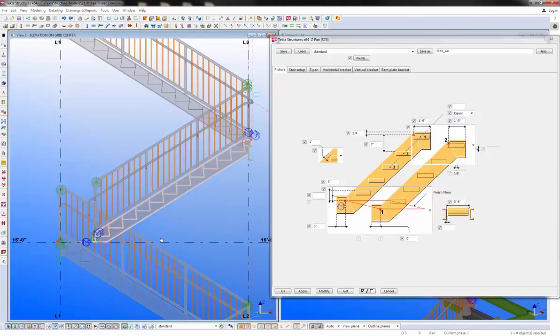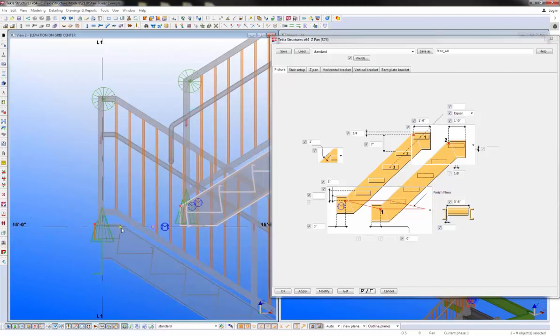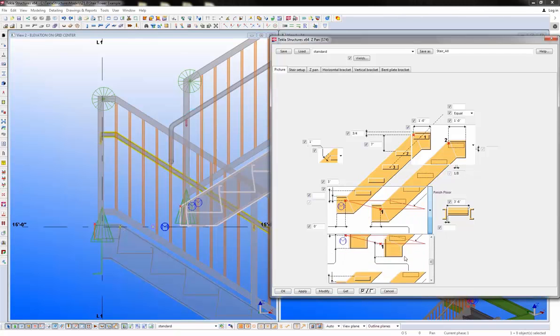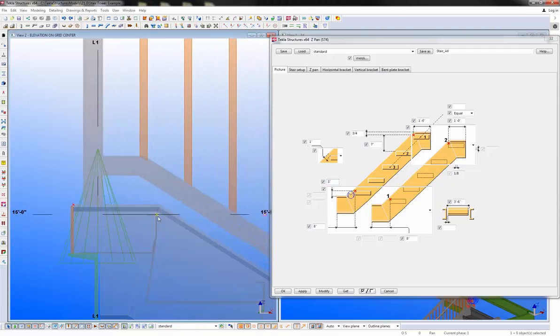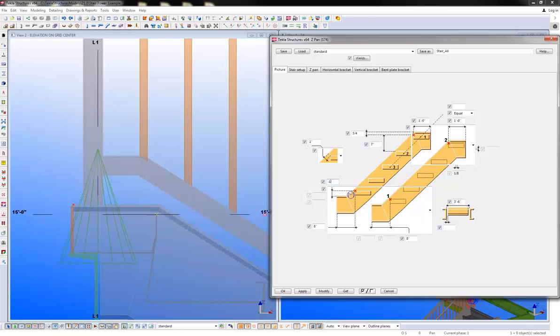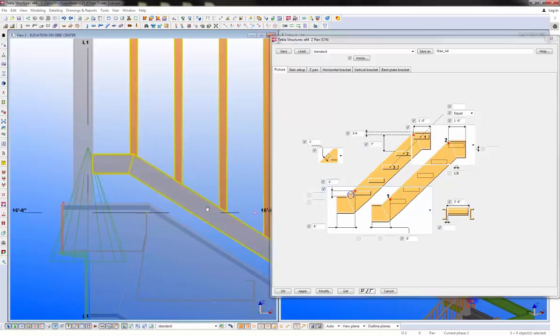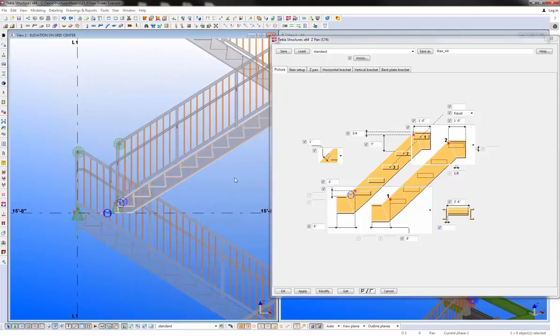At the bottom here, I'm going to be starting from the same nosing point, and I'm going to go ahead and set this so that it will create a tread at that location. And I believe from the nosing out we went 8 inches, so I'm going to go ahead and say 8 inches. And then because I'm going to be kicking up, I'm going to adjust this dimension here. I want the top of my stringer to be 1 inch above the nosing, so I'm going to set this to be a -1 inch. You can see from the dimension properties here. So that should be pretty good to get me started with this anyway.